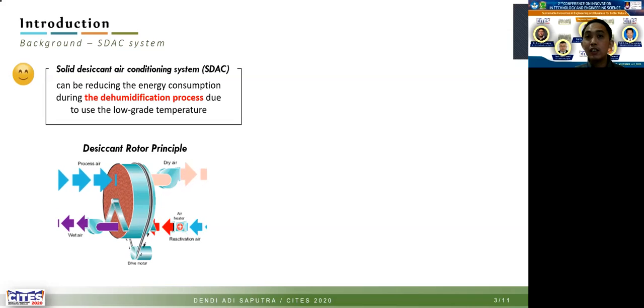The rotor attracts moisture, and when the air leaves the rotor, it will be dry. The dry air is easier, and consumes the lowest energy, to cool using a cooling unit device such as a sensible heat exchanger, cooling coil, or evaporative cooler.